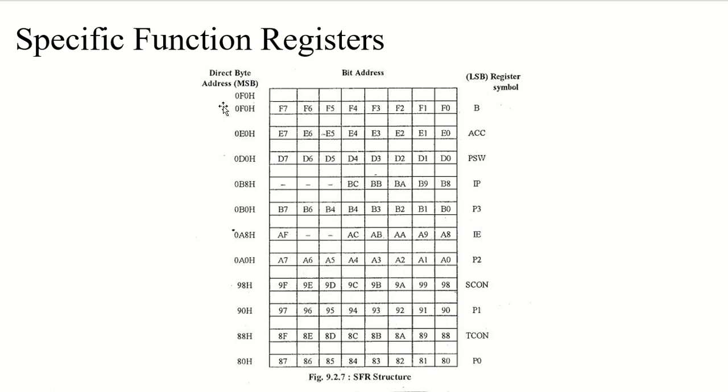See, there is blank space, empty space between this and this and this. This is not decoration; these spaces are not being used here. If we try to use one of these unused locations that are not defined or are empty, then we may get unpredictable results. So it is better not to use the empty or undefined locations in the 8051 microcontroller.